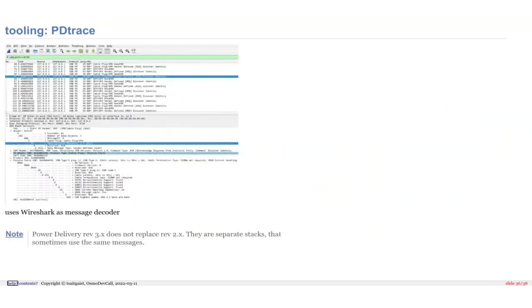And coming to why can't we expand PulseView? Yeah, you can expand PulseView. I decided to go the route to write a dissector for Wireshark, because there are more interfaces to Wireshark, and it's a very powerful tool to dissect all the messages. So I wrote a dissector for the power delivery protocol. It's not complete by far, but the basic things work. At least all the things I've encountered work.